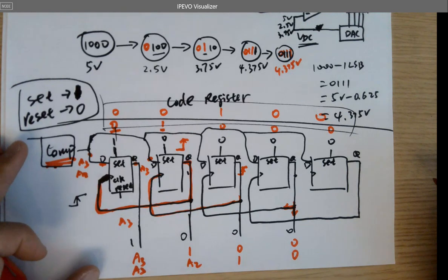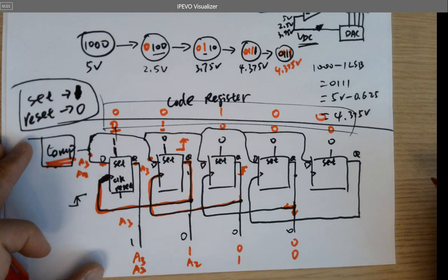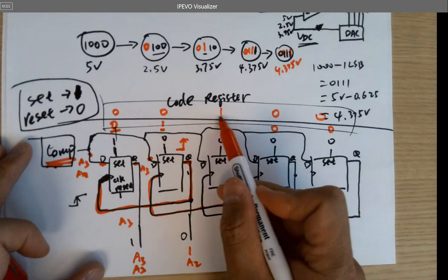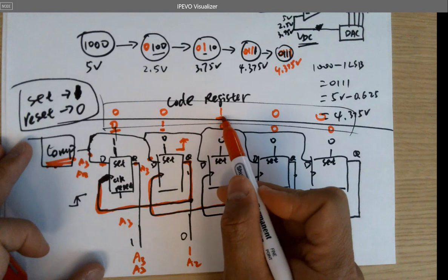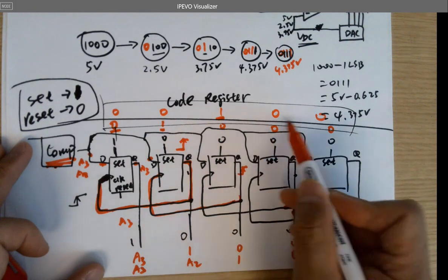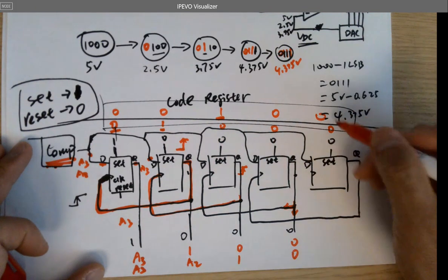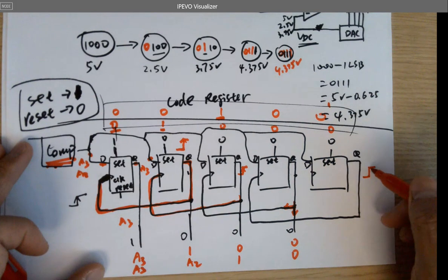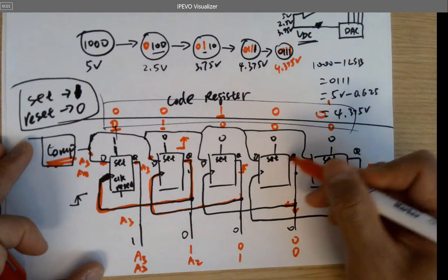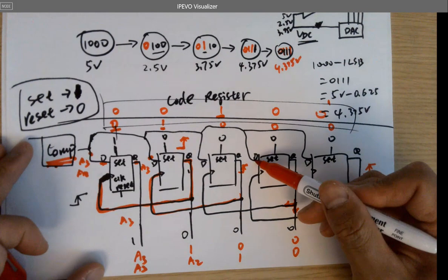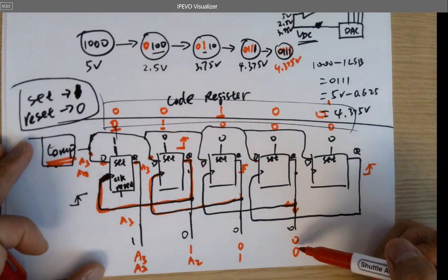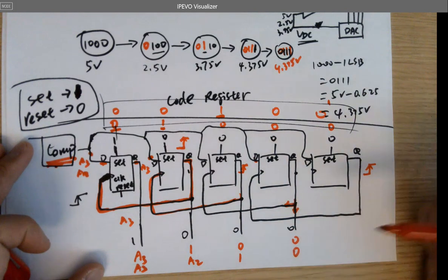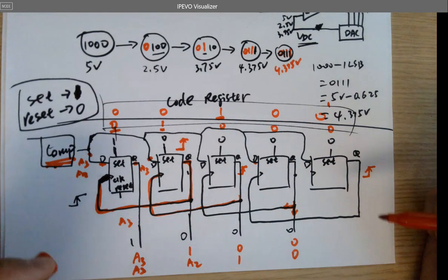So it needs the clock to trigger because there's no rising edge. Remember this little 1 here will keep being shifted to the right, and eventually it will be shifted here. And then this one will be set. There will be a rising edge, and this is going to trigger it, so it's going to register the A0 to here. Make sense?